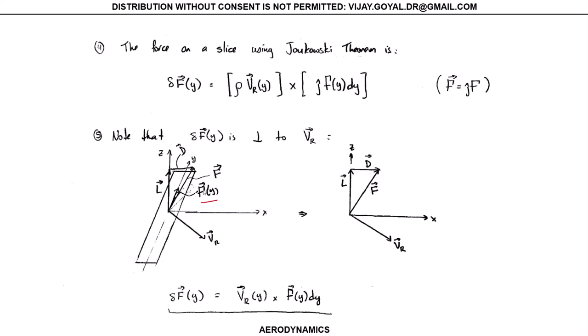a circulation around that. What you can know here immediately is, if I didn't have the induced velocity, I'm going to have this purely. But because now I have an extra velocity that's pushing my aircraft back, and what's responsible for that is my downward velocity, the downwash velocity, then I'm going to have a drag component that shows up.